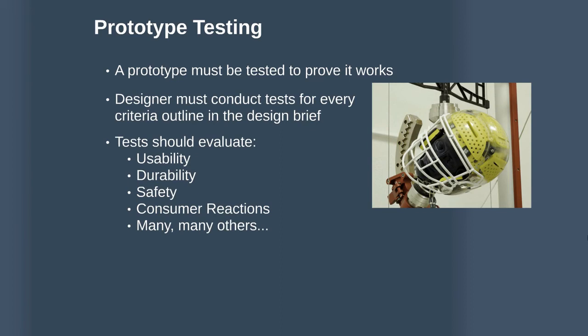The goal of testing a prototype isn't just to find out if it can work once, but to find its limits. If it works once, will it work 50 times? 100? 1,000? If it eventually wears out and stops working, why? What wears out first? Under what conditions will the product fail? What happens if it gets wet? What about if it gets hot or cold? The point of testing the prototype is to figure out every imaginable way that the product could fail in order to determine how it could be improved.